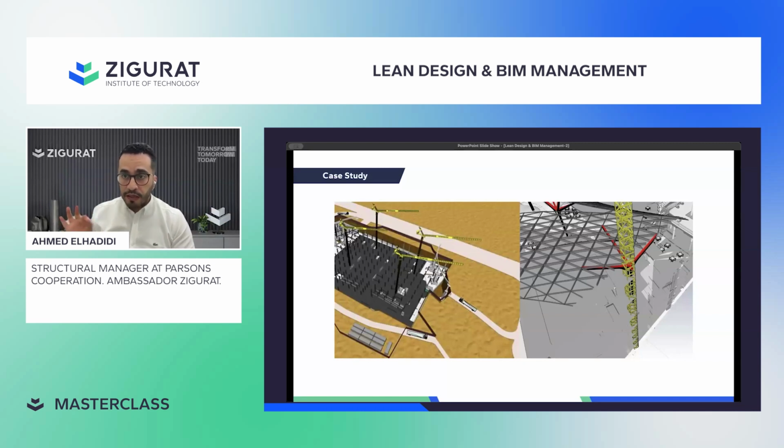Imagine that if he thinks in this lean approach, he will not have this problem, because he will tell the architect, I don't want the full design. Don't focus on the full design. Don't give me renderings or anything. Give me the location of the columns. This is the only thing I want right now. Anything else I consider waste at this current stage, whether it is 6 weeks or 4 weeks. If you give me this location, I can determine the tower crane location, and I can work. So he gains progress. He will not do rework.